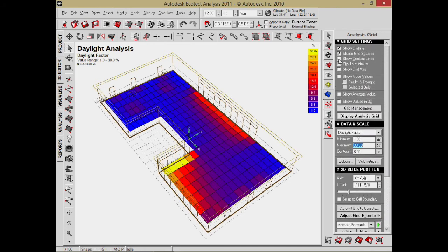That just gives me, again, that information to see where it tapers off. So I can see where the hot zone is, the cooler zone, kind of where the relatively dark zone is. But as you look at this, what do we see? This curtain wall is pretty effective about bringing light in here. The skylights, somewhat effective. Okay, not necessarily doing a great job yet. We might have to do a little work with that to make them more effective.